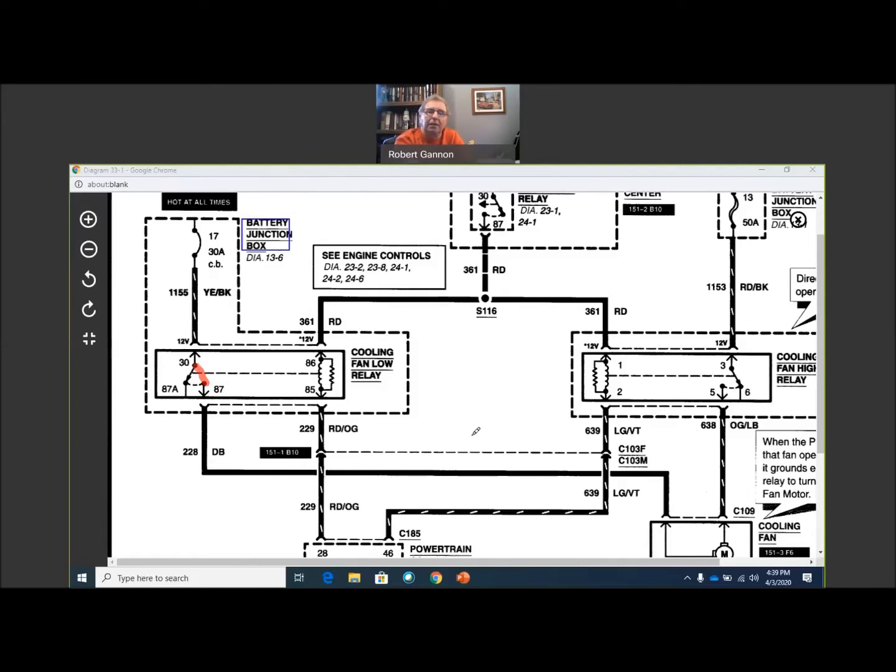A lot of times they stick 5-pin relays in, and they're only using 4 pins. So at 87A, you look down in the socket, and there's not even a terminal in there. It's just blank. Not too uncommon. I could think something like this could be used for low beams, high beams, right? If the relay is de-energized, the power goes out 87A to the low beam headlights. When the relay kicks on, maybe it pulls it over, and now it's going to the high beams instead.